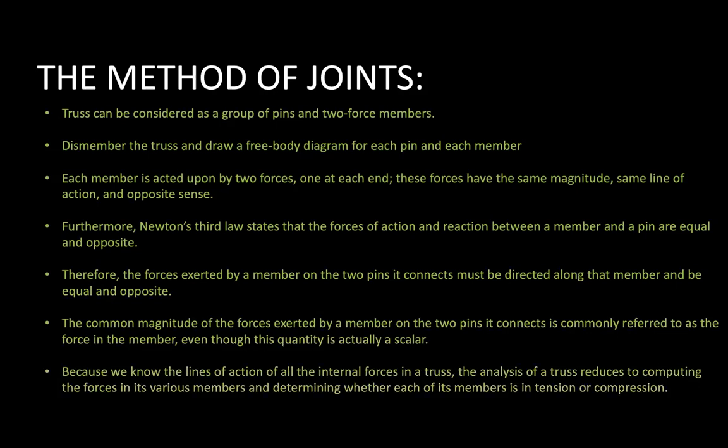Furthermore, Newton's third law states that the forces of action and reaction between a member and a pin are equal and opposite. Therefore, the forces exerted by a member on the two pins it connects must be directed along that member and be equal and opposite. The common magnitude of the forces exerted by a member on the two pins it connects is commonly referred to as the force in the member, even though this quantity is actually a scalar.